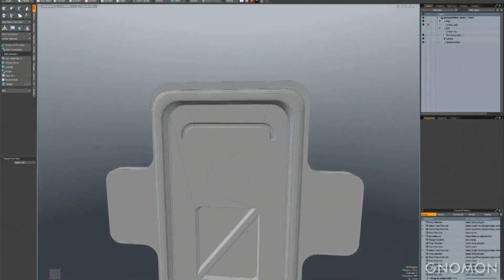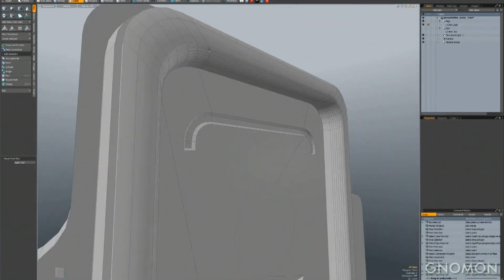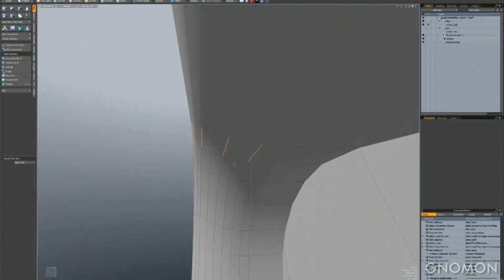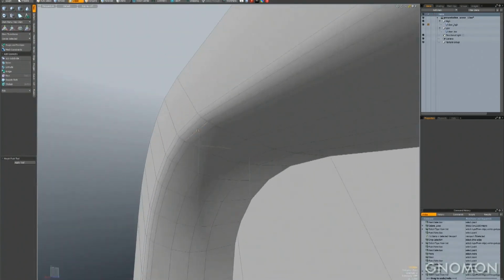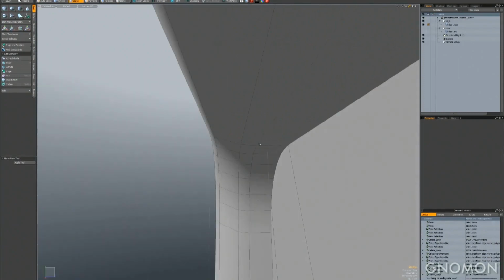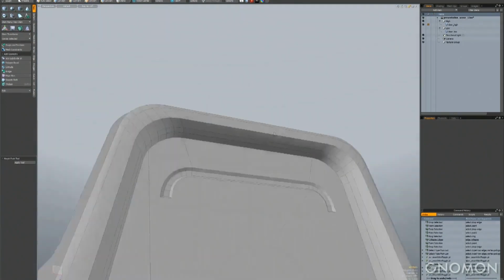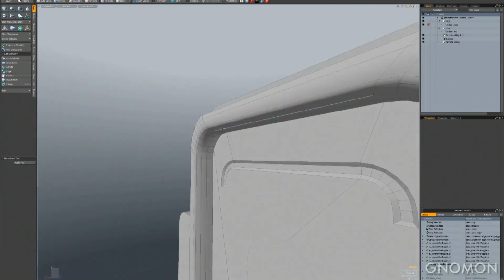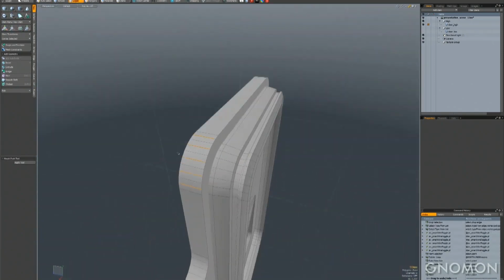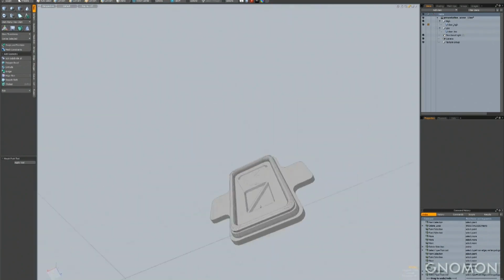That right there is an align to furthest of left, right, up, or down, but based on what you're looking at on your screen, which is one of the best tools I've ever used. I've known people that completely made the switch to Modo based on just one tool like that alone. So it really is just a matter of finding that one thing that wows you and running with it. Right here we'll continue deleting a few more edges, making this low poly.